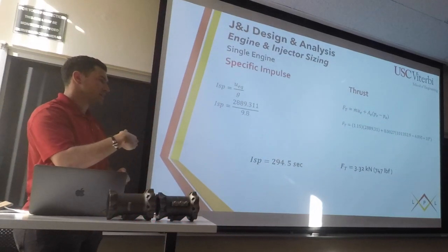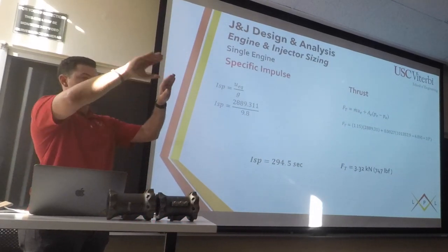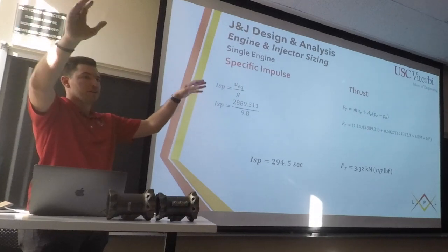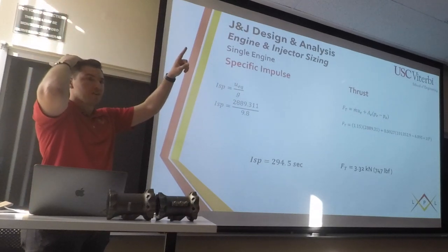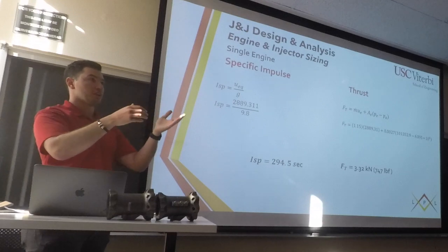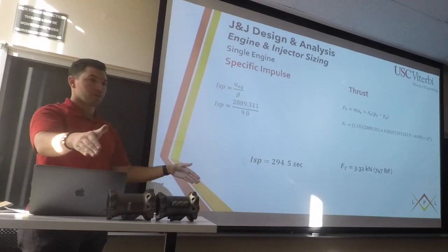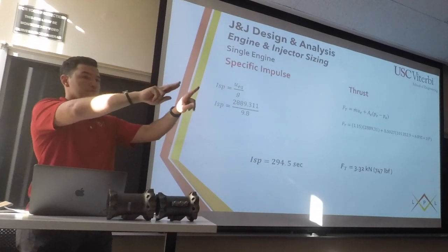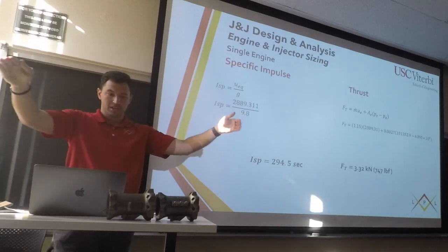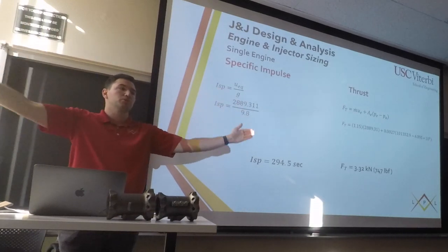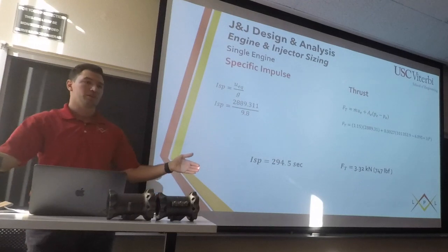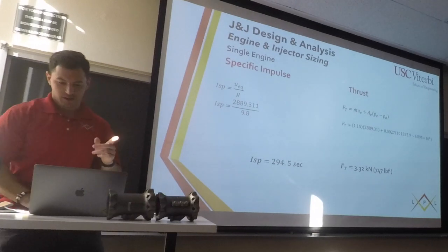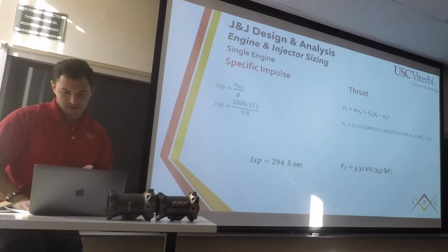And then it's the other way, if it's underexpanded, you'll have a huge plume. That's why you'll see when it launches, when it's going to space, the ambient pressure is getting closer to zero, which means it expands longer. It can't do that, and so all of a sudden, the flow keeps going, right? It keeps making that shape, and that's why it's a huge plume, because it keeps expanding to what it equals outside. So yeah, thanks, Emma. Did I answer your question?